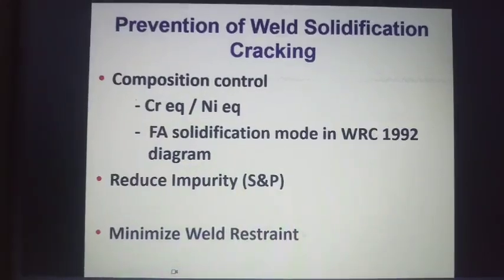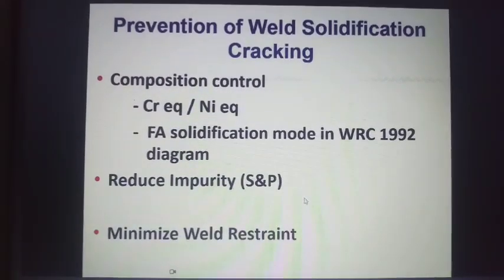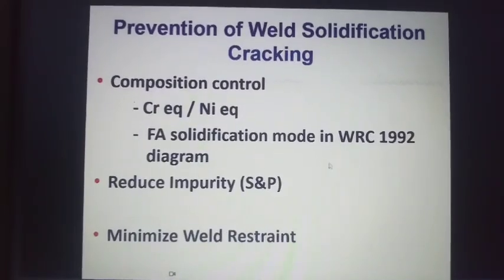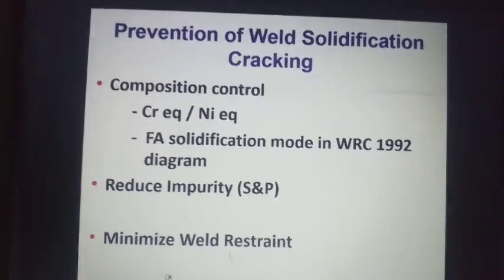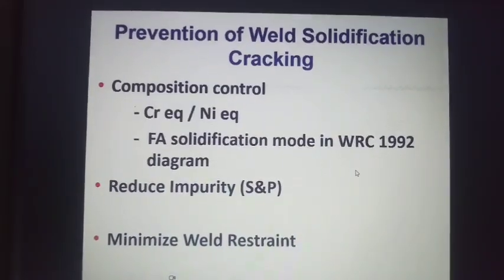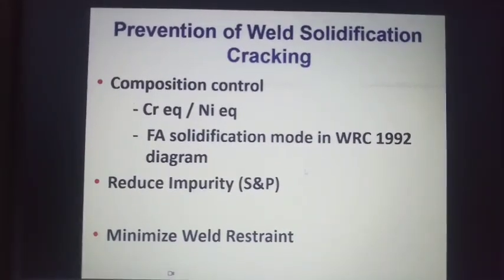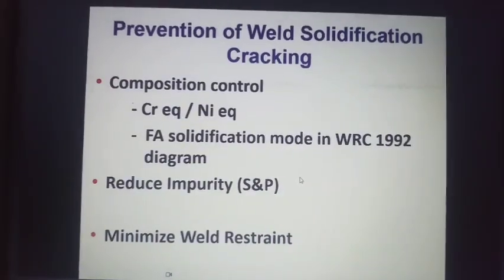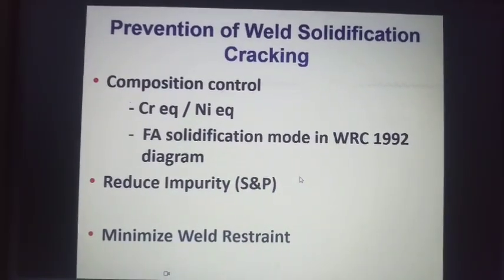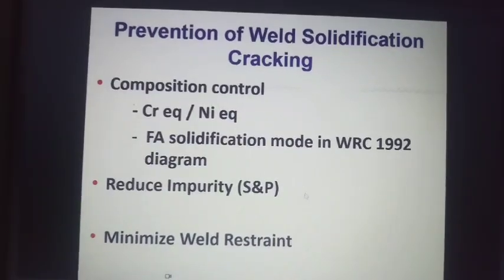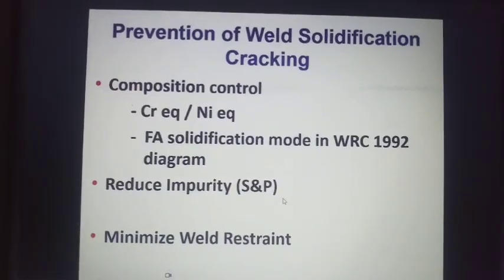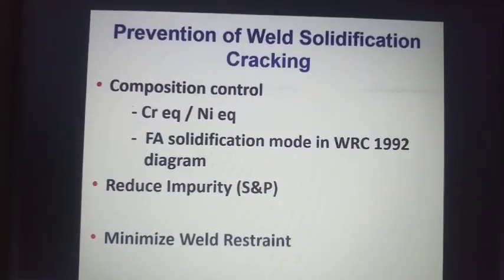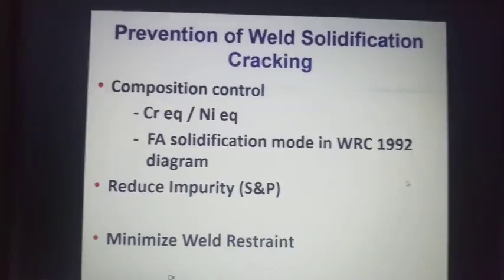If you have a very high depth weld and a low width, then there is a chance of solidification cracking. It is nothing to do with the chemical composition. It is due to the joint restraint, because of which the cracking happens. Sometimes I have seen some companies, to save weld metal, reduce the weld angle. Yeah, narrow groove welding they call.